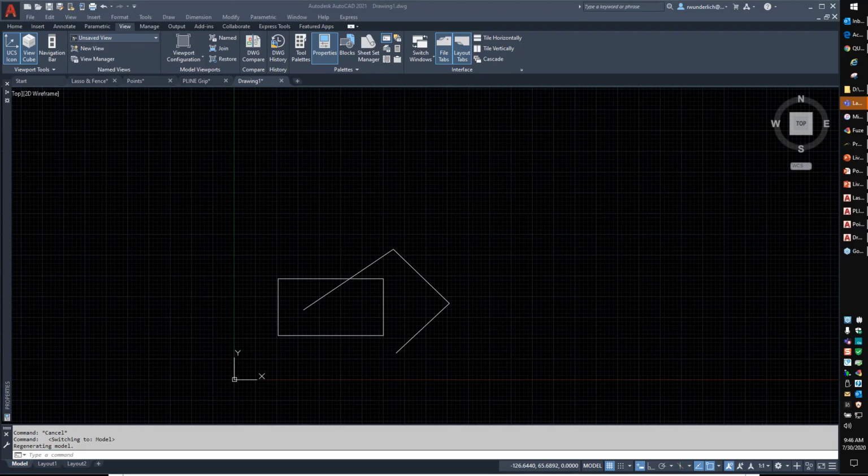All right, we're getting through this. Sometimes when I use the new XREF compare feature, it sets the XREF on a different location in the drawing. I haven't run across that specific issue, Perry, but that could be either the insertion point has been changed between one or the other XREFs, or we may have a separate issue where the XREF compare feature may have a defect, and we would want to take a closer look at that.